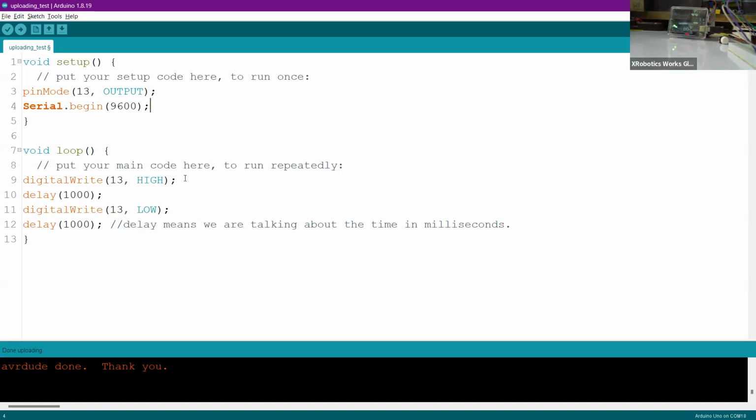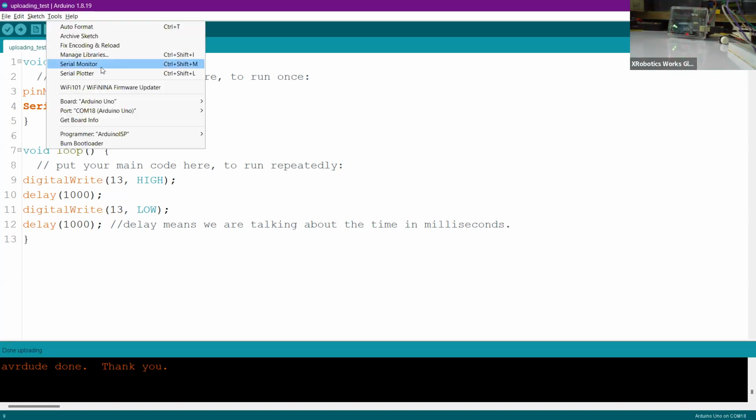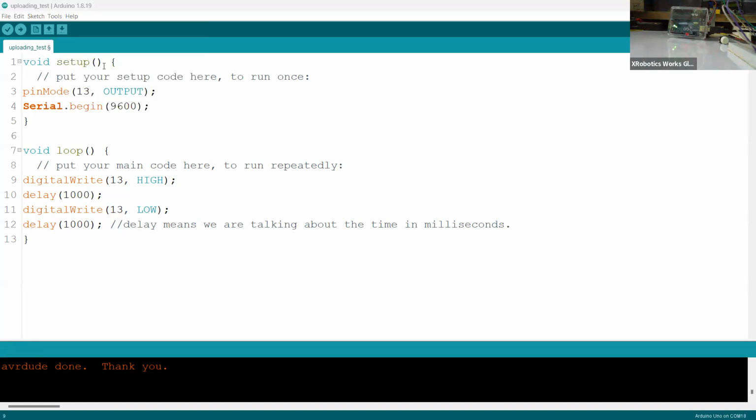To see the actual result on a screen, even if I click on the serial monitor now, I won't see anything coming in the serial monitor, because our controller is not actually responding back to our computer to establish a communication and give feedback whether the input and output devices connected to the microcontroller are executing the task properly or not.